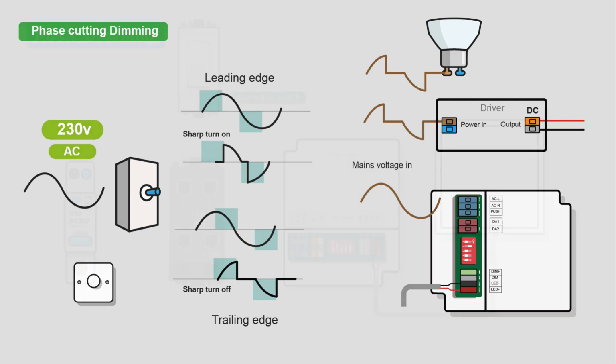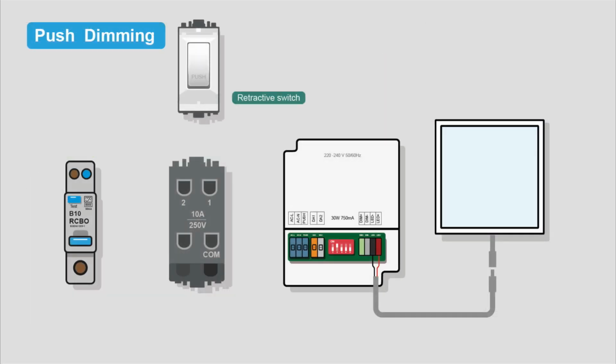Like I say, it's a bit clunky. It's pretty useful. It's certainly not super smooth digital dimming, but if that's not a concern, if you just want to change the settings, not everything is a big office. Could be a church hall or something that just want to have a few panels. So it's a useful and basic type of dimming, which is quite robust. The driver's data sheet says a maximum of 20 drivers controlled by one push switch.